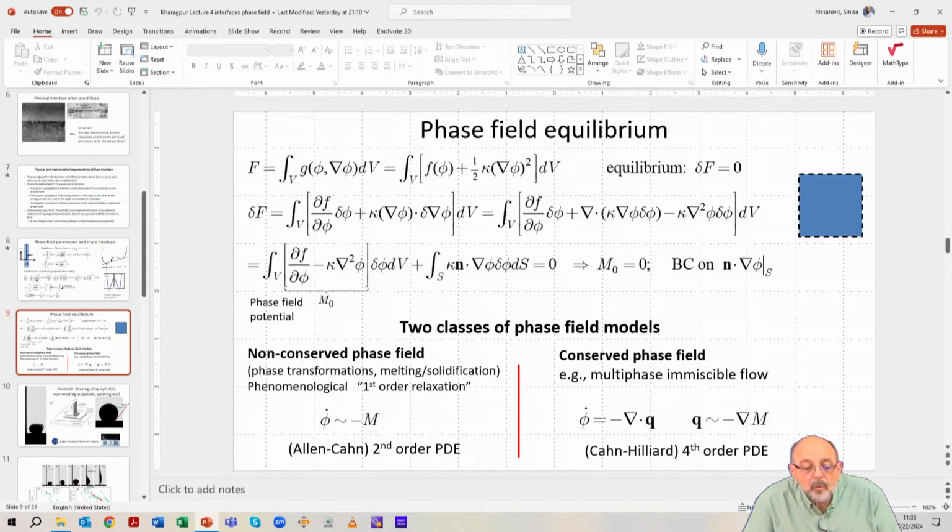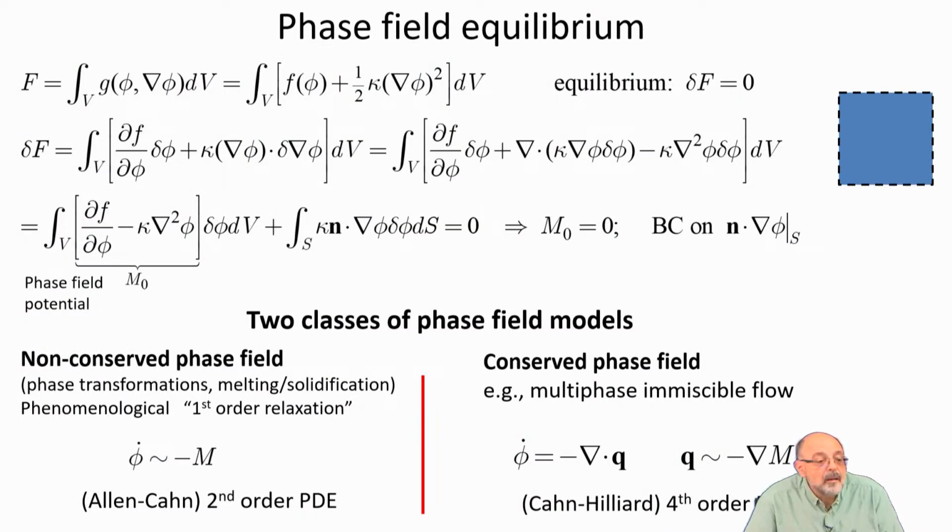Meanwhile, we can continue with our phase field models. The next thing we discussed last time is two types of phase field model: conserved phase and non-conserved phase. For conserved phase, we had to deal with a phase flux. And when you say that the quantity of phase can be only brought by flux, you cannot create the phase, nor destroy it, then your rate of change of phase will be proportional to the divergence of the flux.